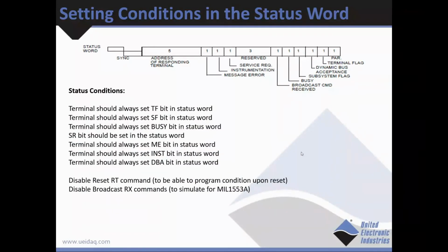The bits in the status word indicate whether a command has been properly received as well as the status of the RT itself. To stress your system, you should have the ability to force errors in these bits to see how the system behaves.